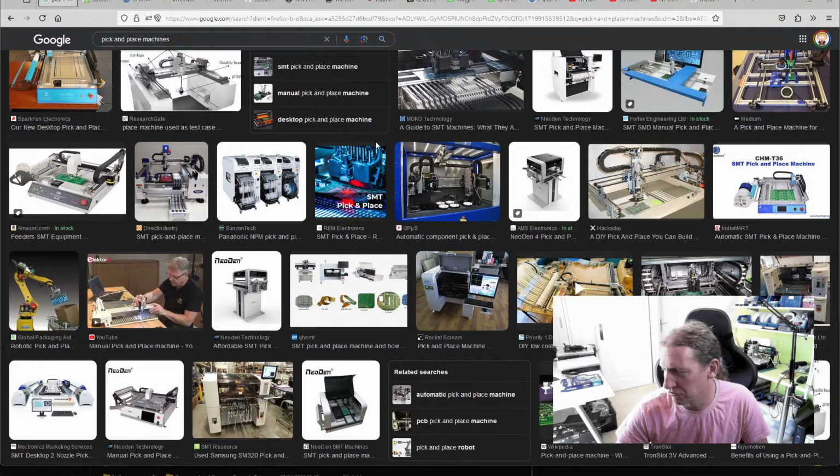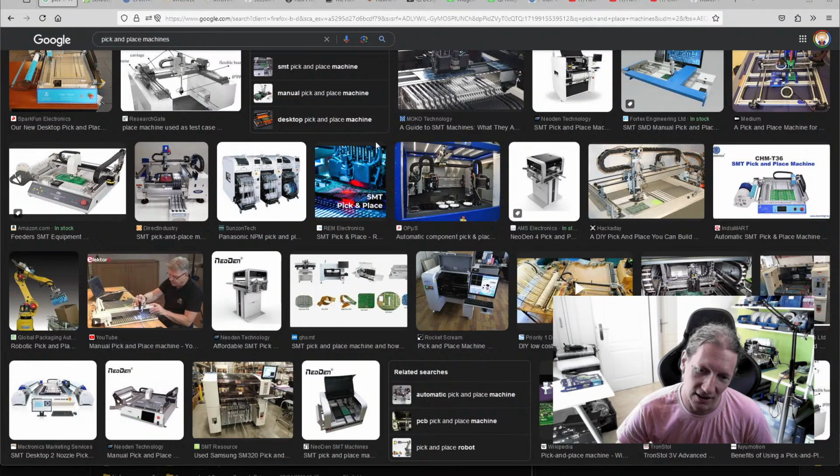There's many other parts of the manufacturing process, such as pasting the board before you put it in the pick and place machine. And then you've also got to put it in the reflow oven after you take it out of your pick and place machine. And before that, you've got designing PCB files, choosing components, ordering from suppliers, managing stock and inventory. And after you've reflowed your project, you basically have to do all the QA testing, putting it on your website and shipping it and everything. The pick and place machine is one small but very critical part to this whole process.